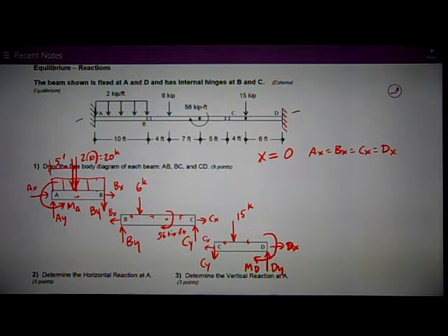So there's no X forces, and there's nothing out of line. If I was to take any moments, any X forces are going to cancel out, zero out through the point, whatever point I'm taking the moments about. So now I'm ready to analyze. The only one I can start off with is BC, because it has really 2 unknowns and 2 equations, sum of forces in the Y and the sum of moments.